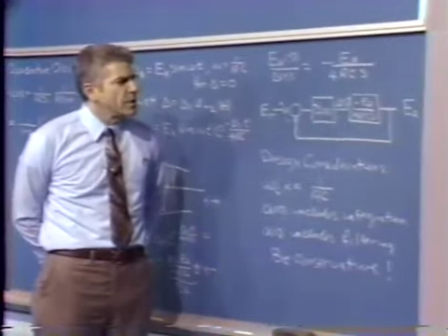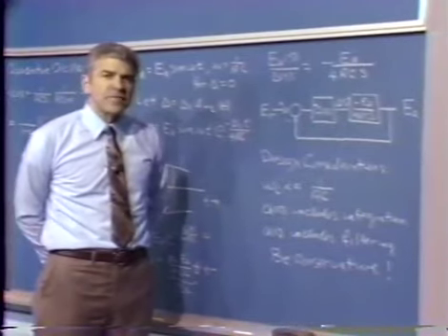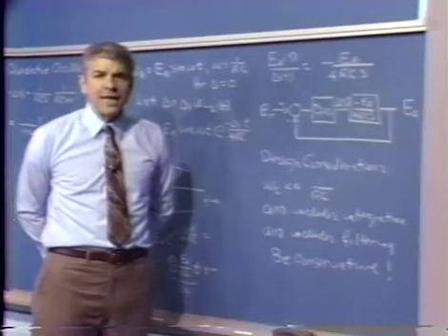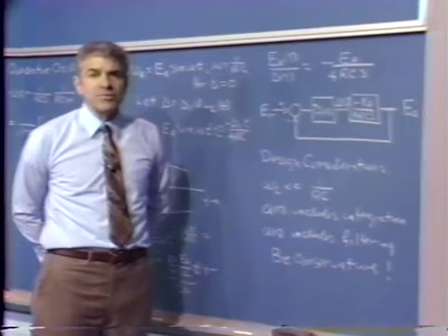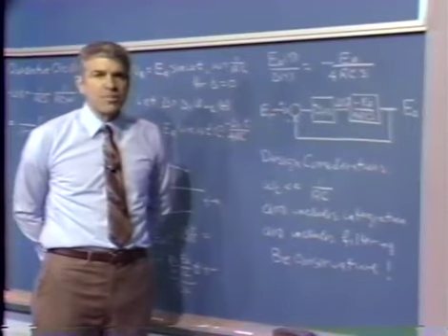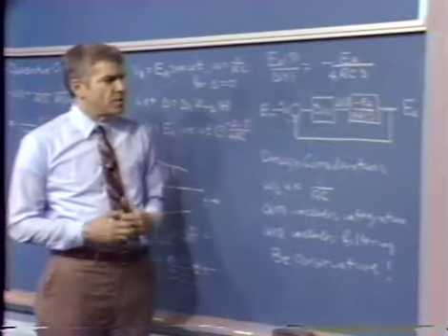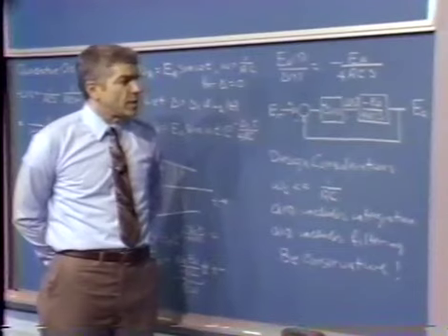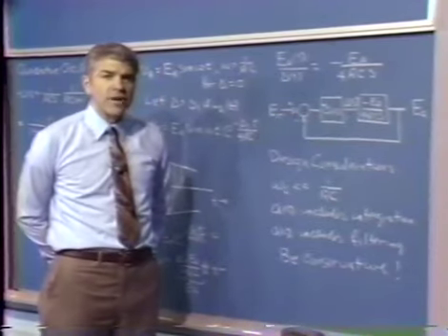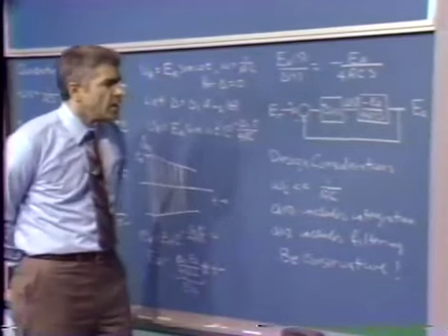That sort of behavior, incidentally, always occurs in gain control kinds of things. You invariably find out that some loop transmission parameter, some loop transmission magnitude, is dependent on operating point. It shows up here in our amplitude stabilization loop by virtue of the operating point value of the envelope coming in as a multiplicative factor in the loop transmission.